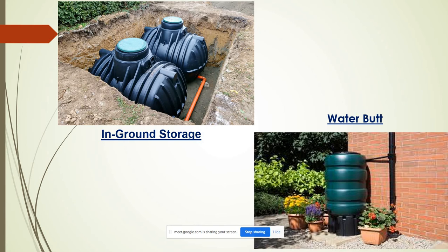Retention pond: retention ponds are used to collect surface runoff water and improve the quality of water by natural processes like sedimentation, decomposition, disinfection, and soil filtration. In-ground storage: underground storage tanks are very popular in areas where the majority of rainfall occurs in one single season. These underground tanks are insulated and have a very low rate of evaporation. And these are the last pictures, examples of rainwater harvesting system methods, indirect pump and gravity only. Thank you.